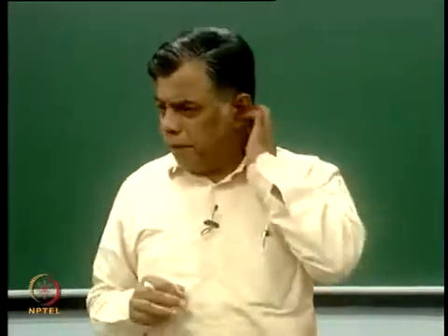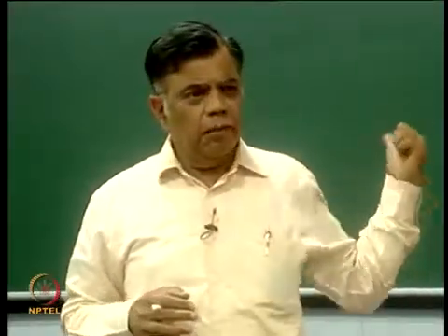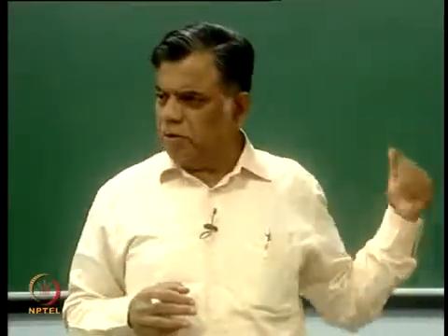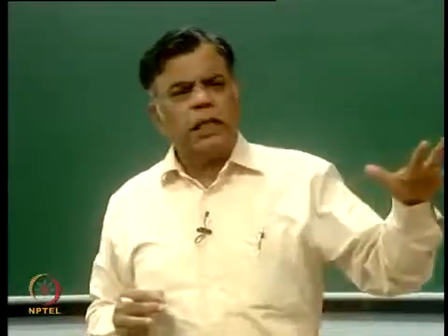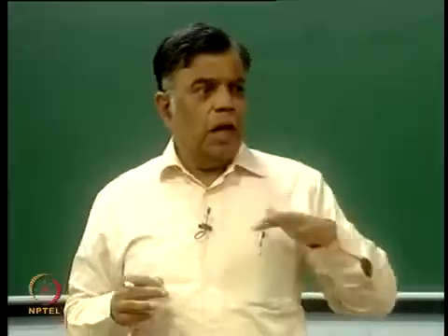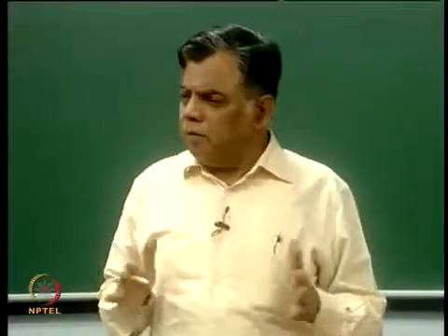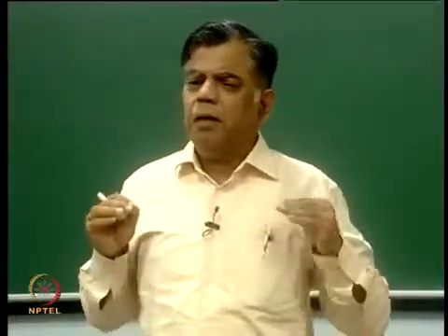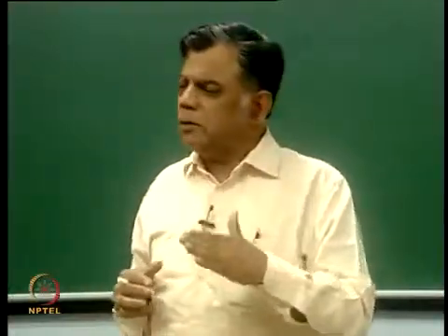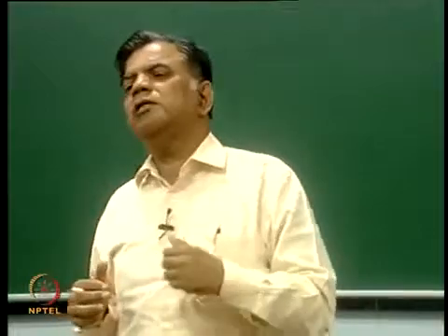Prandtl, Ludwig Prandtl. Please find out about his life. You have a book by him in the library, a green bound book. Please go and study that. Ludwig Prandtl proposed, after studying the Navier-Stokes equation, after a lot of experimentation, he was the first one to propose that shear stresses are very important, it is all very fine, but these are important only in a very thin layer adjacent to a solid surface on which the fluid is flowing.